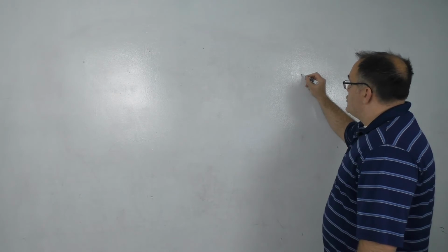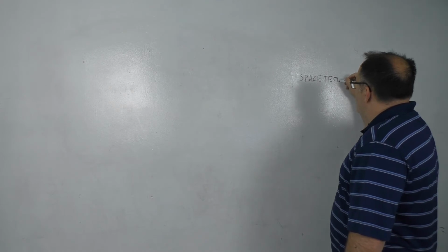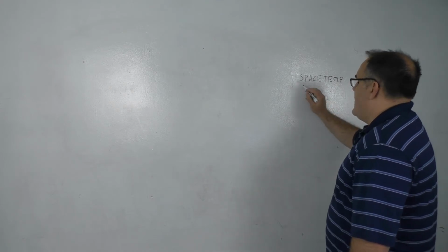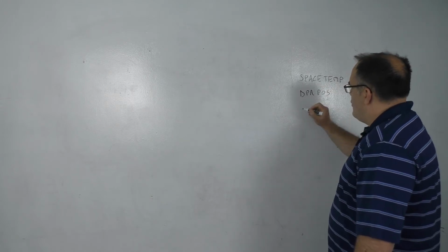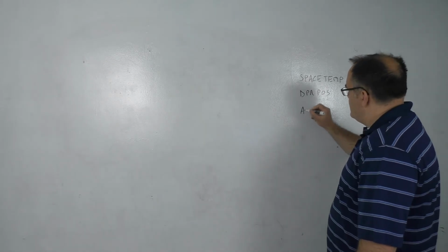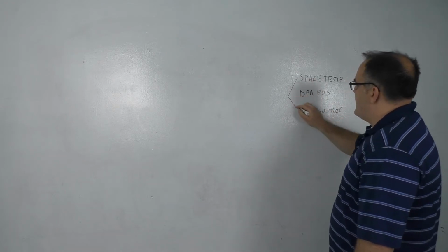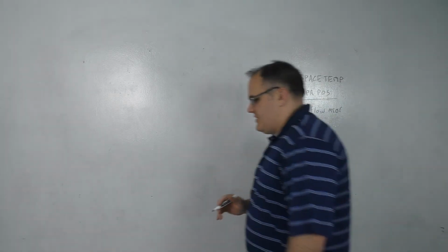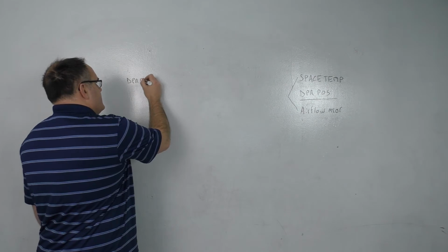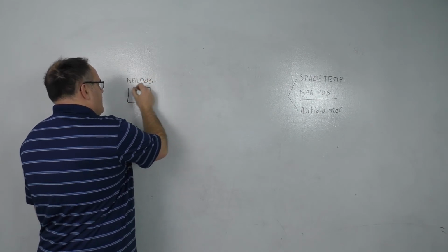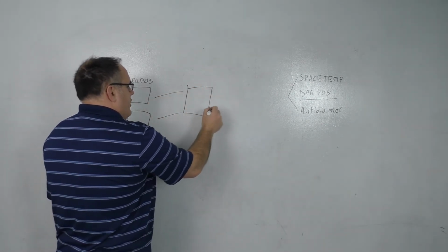So trim and response based on demand is looking at the same demand factors that we've seen in the past, which could be space temp, we could say damper position, we could say airflow. These are kind of the main areas, but the main one is going to be damper position. And essentially what is happening is we're taking the damper position from a bunch of VAV boxes, and we're sending that to a central controller